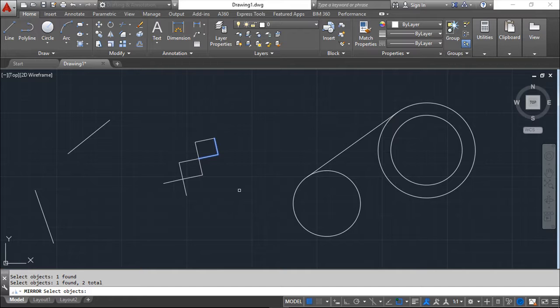If I go to the R key on your keyboard, R, and then enter, you see now that it is saying remove objects, and I want to remove this one. It is asking for more, or I can go back to the add mode, A, enter, again, select. So in any selection mode, I can use this functionality.